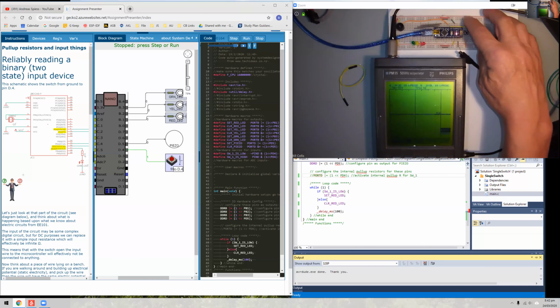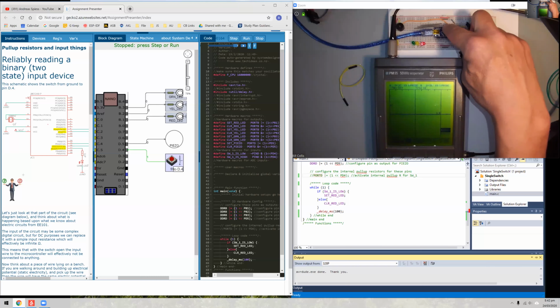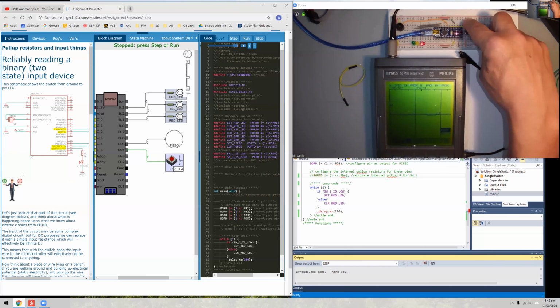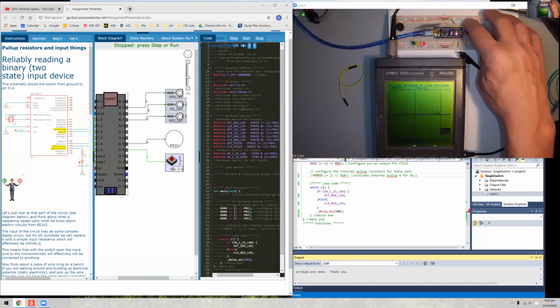And when I touch this, you can see that actually I'm putting 5 volts on the circuit, and my LED is doing strange things. It might be on or it might be off. It's gone on at the moment. Let's touch around my circuit a bit more, see if we can get it to, I'll reset it. No, so our pin is just all over the place in terms of voltage.